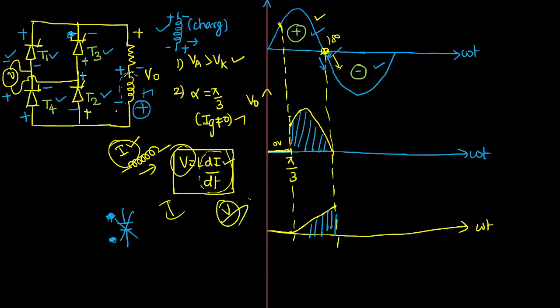Now that case will not happen, at least for some time. Sometime means, see, this negative supply keeps on injecting negative energy. This negative energy will be opposed by the positive energy stored across the inductor. After some point, what will happen? Till that point you can observe the supply voltage will come through thyristors T1 and T2, and it will appear across the output. It will continue. I know it is negative voltage. That negative voltage will start appearing across the output terminal because the energy stored across the inductor will freewheel through thyristors T1 and T2. So it will allow the negative voltage till some extent.